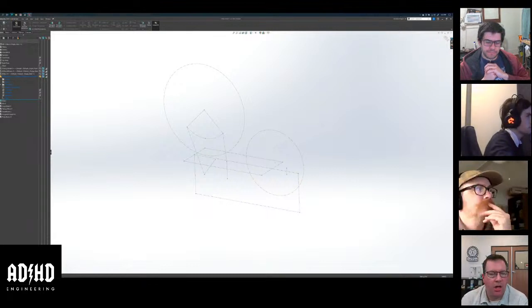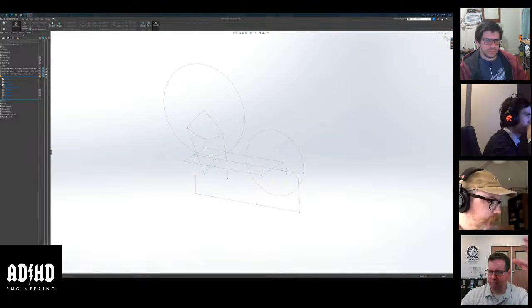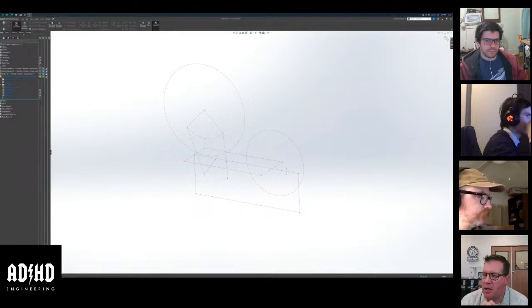Oh yeah. Now go ahead. No, I was going to say that's one of the things where I was thinking we would have all of the information in the skeleton, right? So each of the points where a PMMA pipe originates would have a dot and a circle, well, a circle with a center point. And if things move, then the start and end move themselves. You don't have to redo that sweep. Yeah, we have to have the entire path of the line in the skeleton, so that it doesn't intersect with the other pipes somehow. Yes. And I'm super excited for doing those 3D sketches in SolidWorks. I'm like, yeah, that's going to be good.